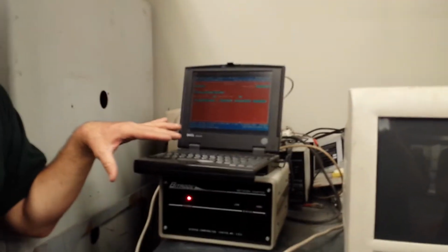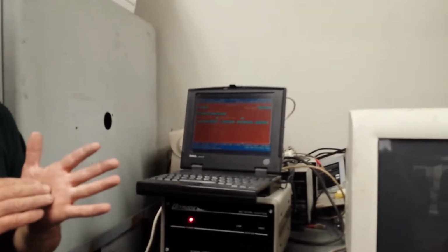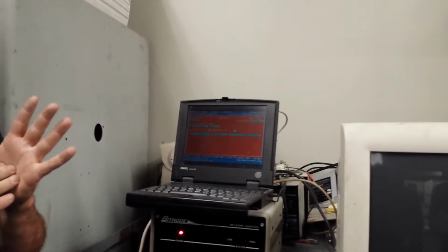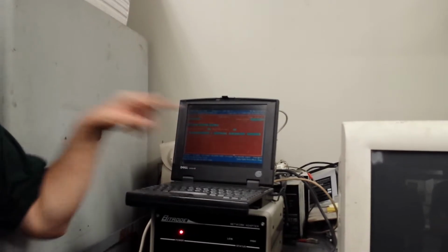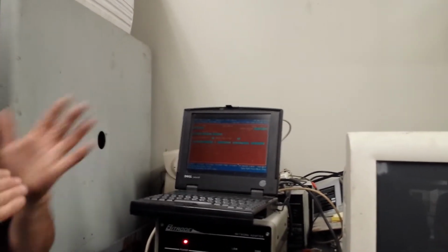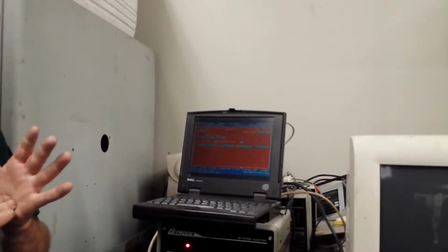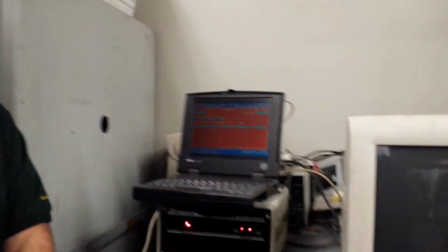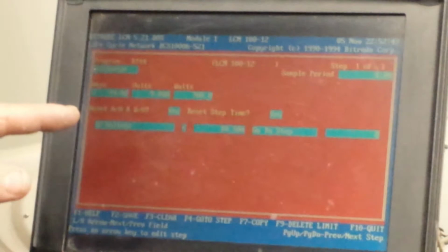So that's an important concept on how this box works. You can set different parameters. Whatever limits first will limit the program. So if I put 100 watts there, it would limit on watts. If I put 11 volts, it might limit on volts, right? But I've got 9 volts, which is much lower, and 700 watts, which is too high, so it's going to limit on amps, right? That's the engineering behind it.